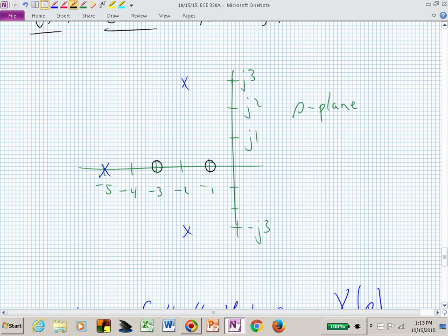And if they are off of the imaginary axis, they're damped. They're exponentially damped sines and cosines. If they were right on the imaginary axis, they never decay. There's no e to the minus, there's an e to the 0t. They're just shaking. You hit it, you get it started, and then it just oscillates. If you had an oscillator, you would have poles on the imaginary axis.